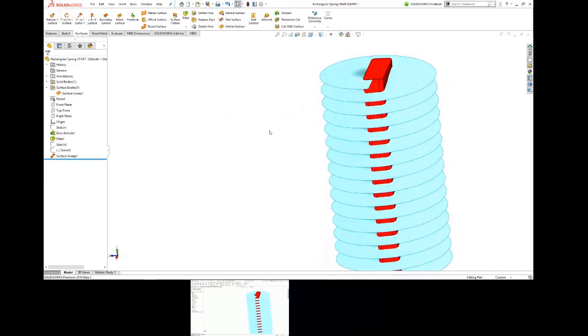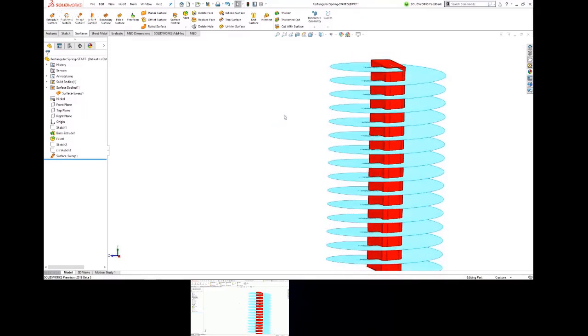So there's my helical reference plane, so to speak. Now the trick is just to project that helical surface onto the rectangular body so that I could get a curve out of it. Because if I can get that curve, now I can sweep my real profile. Does anybody have a clue on what the tool is we'll use for this? Surface intercept. Ooh, close. But really what I want is a curve or a sketch out of this.